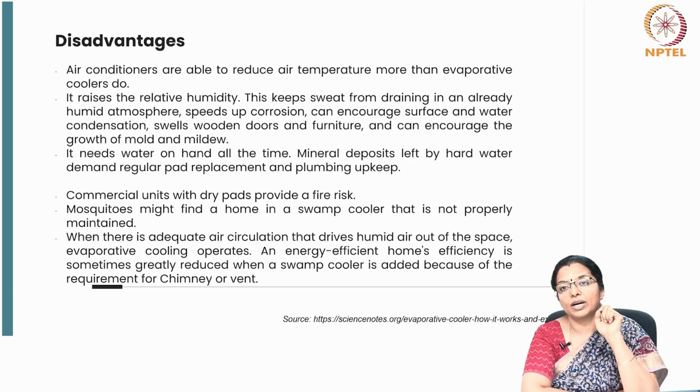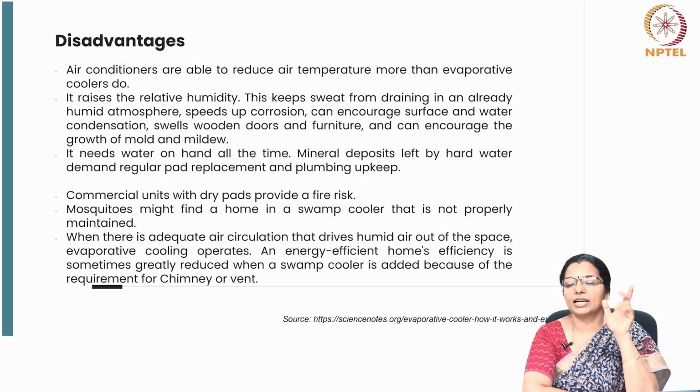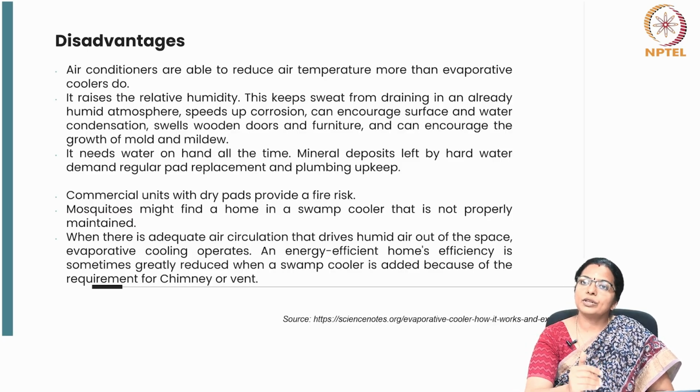The biggest disadvantage of this system is that unless it is well maintained, the growth of mildew, mold, and fungus can have a very negative impact on people's health. And these are too small to be seen by the naked eye. So, regular cleaning and maintenance is a must if this technique is to be used in any form. Because here we are talking only of the principle. How you translate it architecturally is entirely up to you.